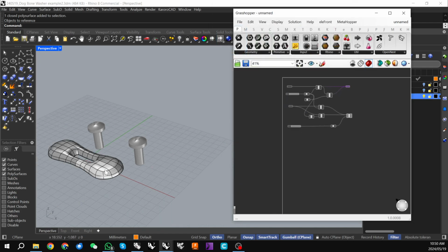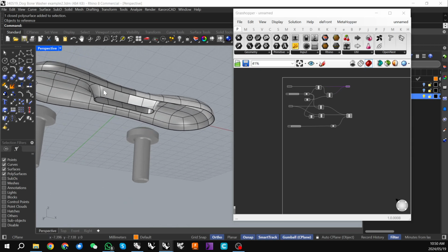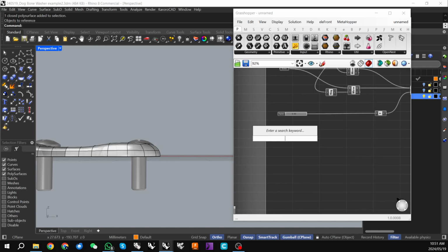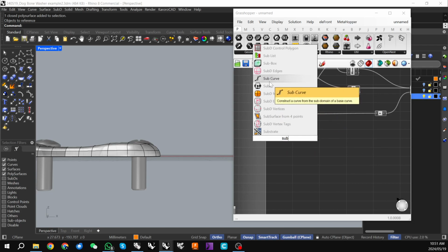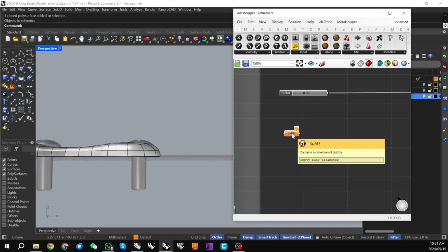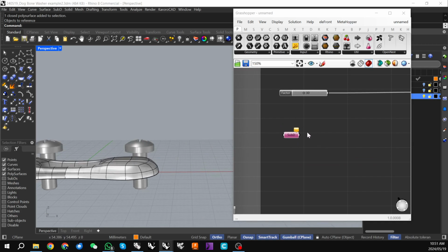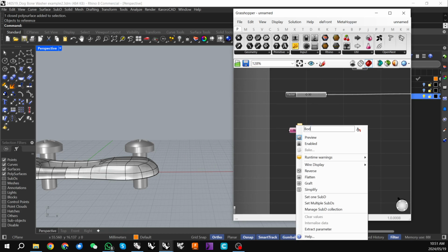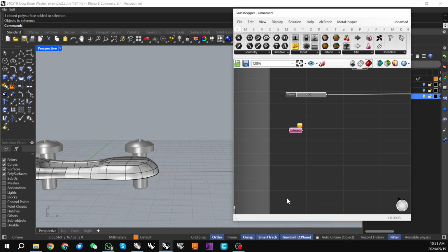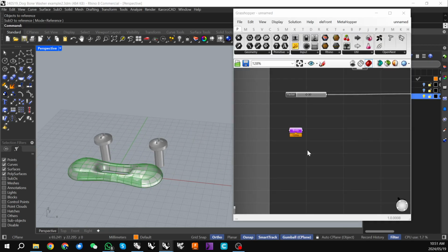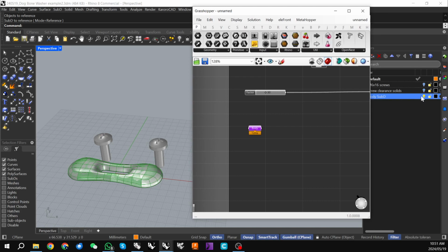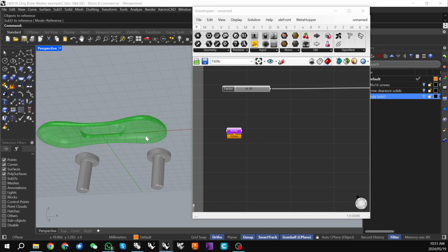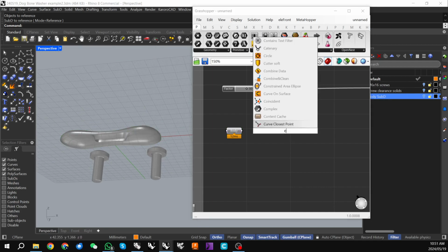So finally, what we need to do is bring the sub D body in, and we see that this is open on the bottom. But we can come here, go to sub D, and you really need to bring a sub D model in using the sub D type. So we'll just call this body, and we can set one sub D, and I'll turn that off here. Because this is open from the bottom, and I really need this as a solid object, the first thing I'm going to do is a cap.